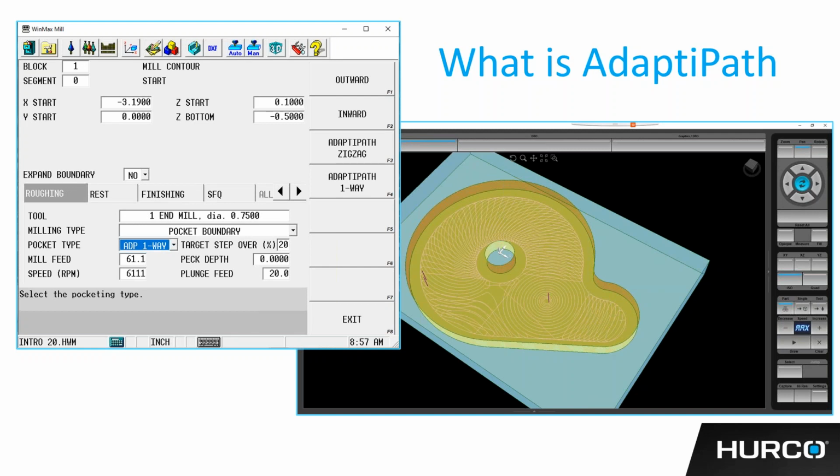This is a roughing strategy. It's meant to remove material very quickly. So you will typically use a finish pass with this as well. If you don't leave a finish pass, if you do have finished sidewalls, you will see a little bit of marks on those sides because this is intended to be a roughing strategy. It is meant to remove a lot of material very quickly.